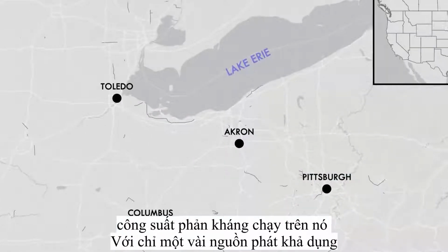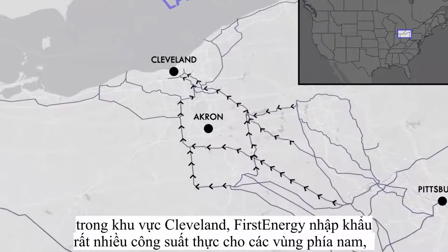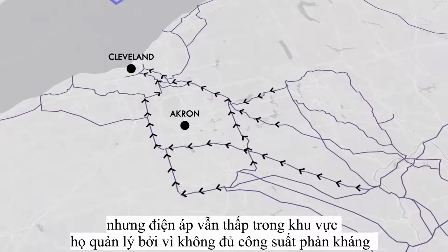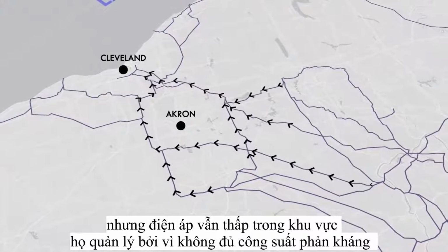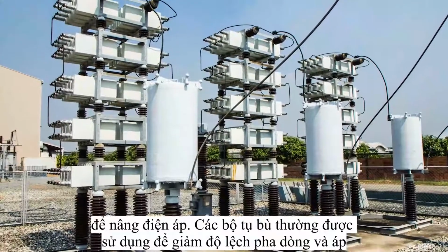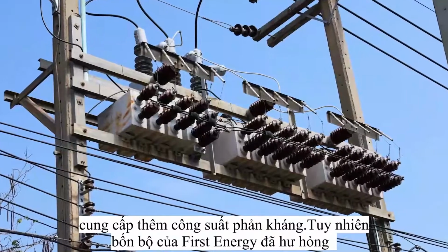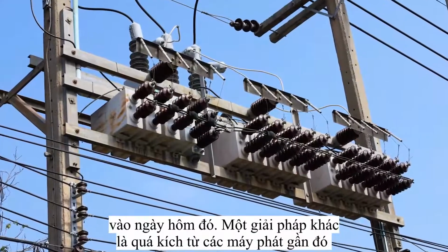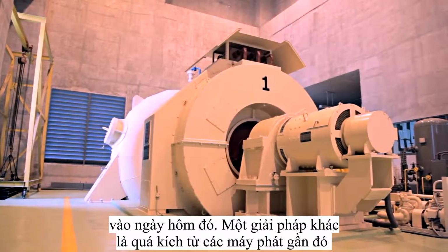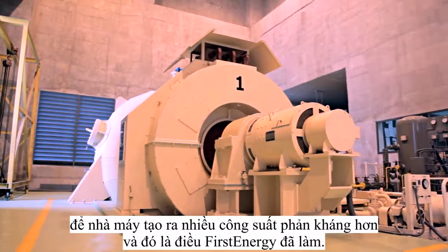With only a few running generators within the Cleveland area, First Energy was importing a lot of real power from other areas to the south. But voltages were still getting low on their part of the grid because there wasn't enough reactive power to go around. Capacitor banks are often used to help bring current and voltage back into sync, providing reactive power. However, at least 4 of First Energy's capacitor banks were out of service on the 14th. Another option is to overexcite the generators at nearby power plants so that they create more reactive power, and that's just what First Energy did.